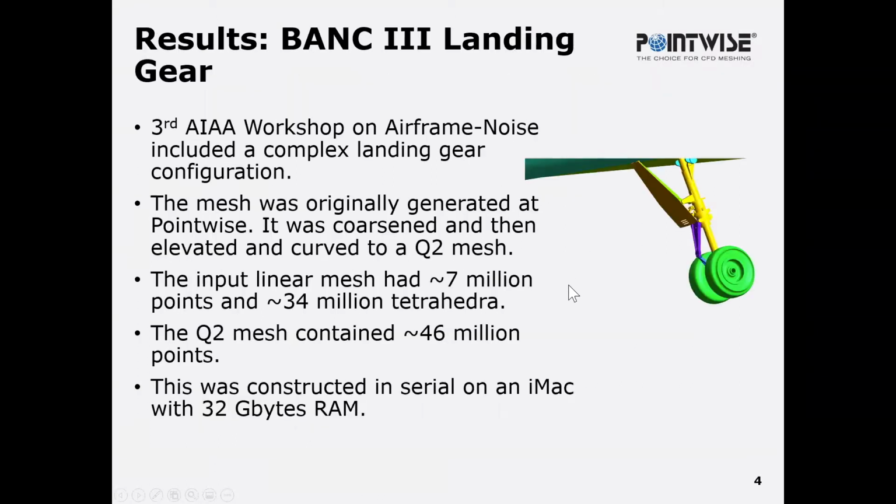I just wanted to show a quick example of what's been done so far with Pointwise. This example has come from the third AIAA workshop on airframe noise, and it's a complex geometry of a landing gear configuration. And this was shown in an earlier presentation by Mark. But this mesh was originally generated at Pointwise, and it was coarsened and then elevated and curved to a quadratic mesh.